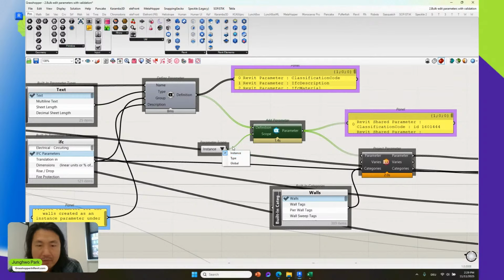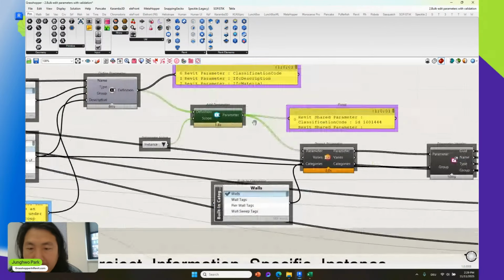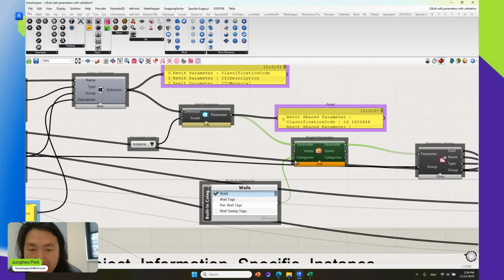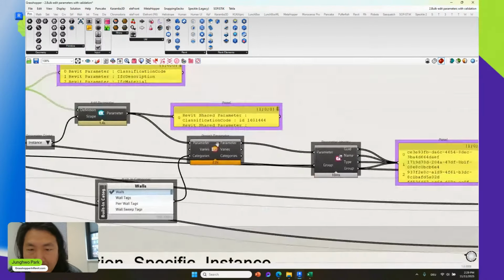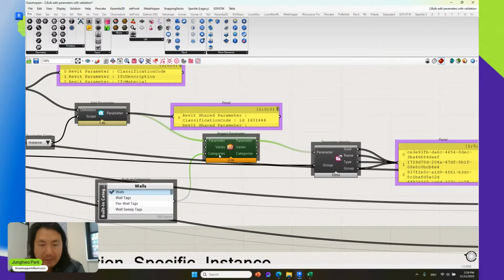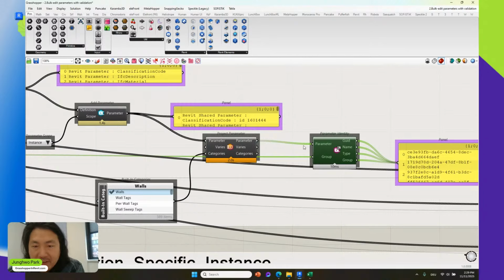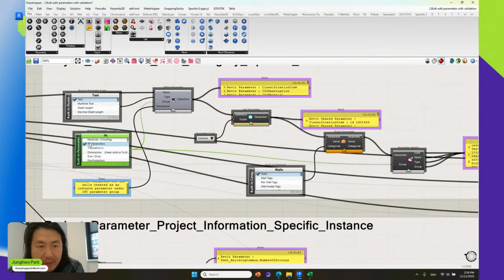In Revit, we have 3 different parameter types: instance, type and global parameters. We'll add at the moment as an instance parameter, and we will provide category too, because we are defining this project parameter for specific Revit entity, Revit category, sorry, mixing up with the IFC entity, but yeah, wall category. And then from there, we'll feed this parameter to the group, which is the IFC parameter group.